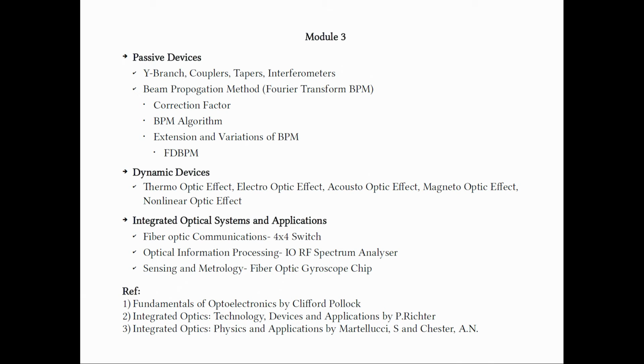So, one of the important features of the electro-optic effect is that it could be very high speed. We can consider the electrodes as coplanar strip lines, and the high frequency RF or microwave signal can be considered as propagating on these electrodes and creating a travelling wave, which can affect the light propagation in the optical waveguide. So, there is a microwave coplanar strip line, a microwave waveguide on top in terms of the electrodes, and an optical wave in the waveguide.